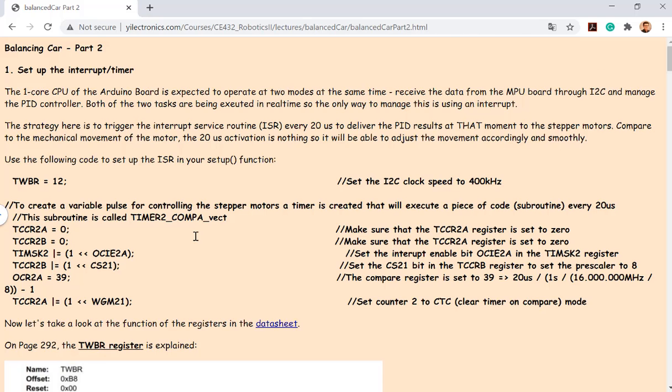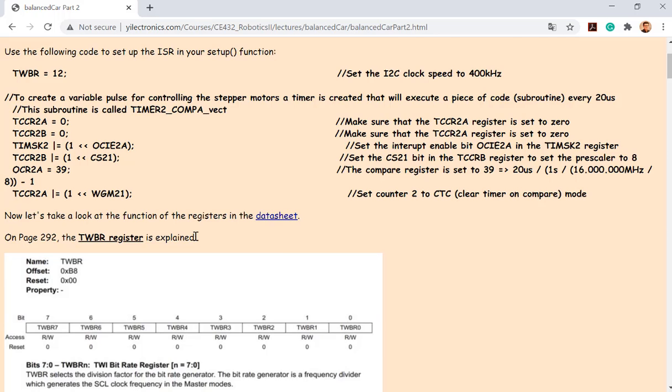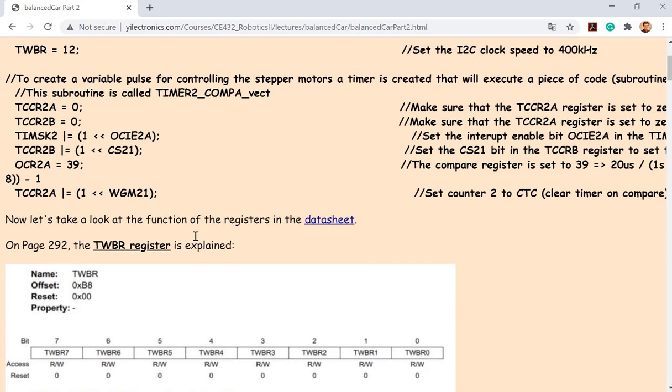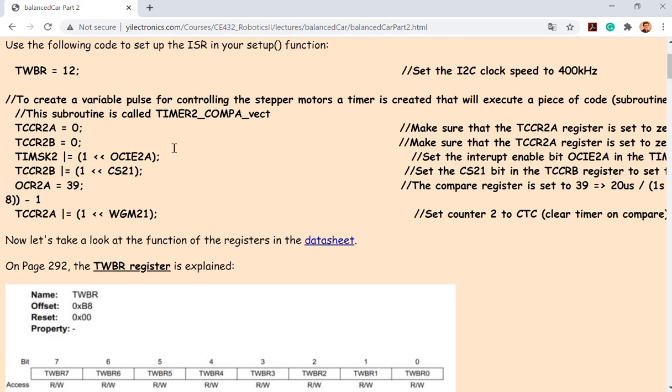Let's take a look at part 2 of the tutorial. I think I went through the interrupt in the microcontroller class, did I? For you guys, for group 2? So that's timer 2. It can do the same job, but the only difference is that timer 2, I think, is only 8-bit. Timer 1 is 16-bit. So for a matching number, you couldn't use anything larger than 2 to the 8th, I think.